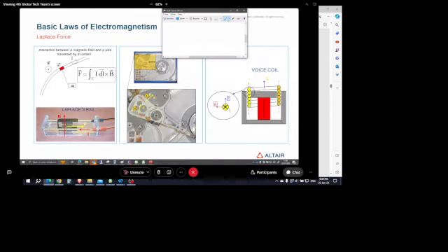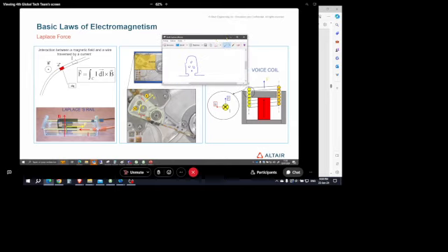So if I plot the stator slot like this, and you have the wires, when you supply your coil, there is always this canalized magnetic flux, but there is as well some leakage magnetic flux inside the slot.